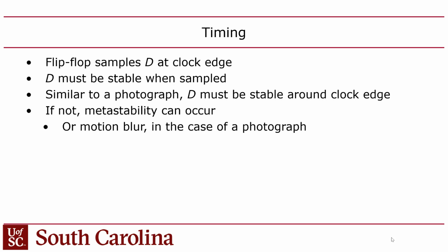But the time it takes to do that is an exponential random variable, so we don't know. Could be within the clock cycle, could be after. But suffice it to say, if you go metastable, then you can throw the contamination delay and the propagation delay of the flip-flop out the window, because there are no more promises. The flip-flop is no longer beholden to its stated contamination and propagation delays. Now, it doesn't permanently damage anything, and it doesn't brick your device. It just puts it in this weird in-between state for a while.